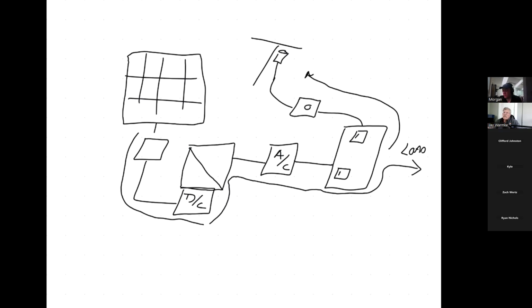Well, the impact of that is, if you start adding lots of power to the grid, then the grid's voltage is going to increase, right? Because all of this voltage that you're dumping onto the grid slowly elevates the voltage of the grid itself. So if you've got 100,000 homes and they're all pumping power out onto the grid, the voltage is going to elevate.